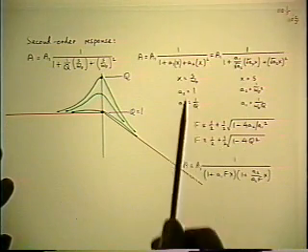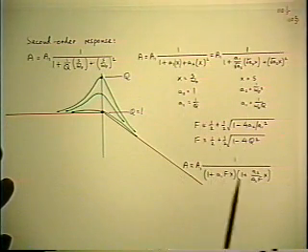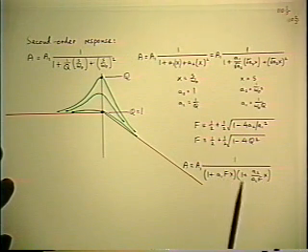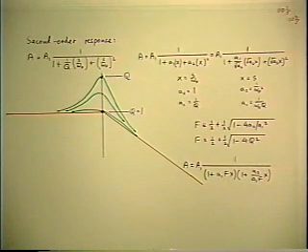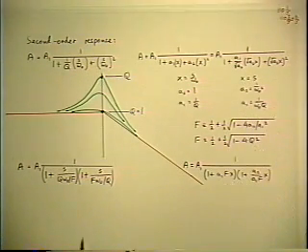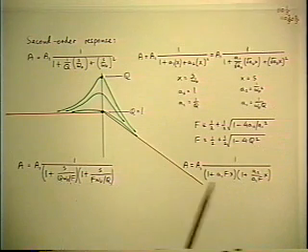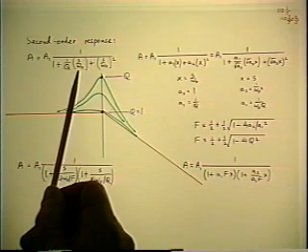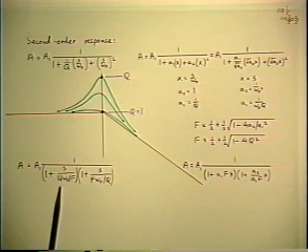So we can express the quadratic in terms of the product of two root factors. Here's the exact result, retaining the F. And here it is, the same two factors in terms of the Q and the corner frequency of the original quadratic.